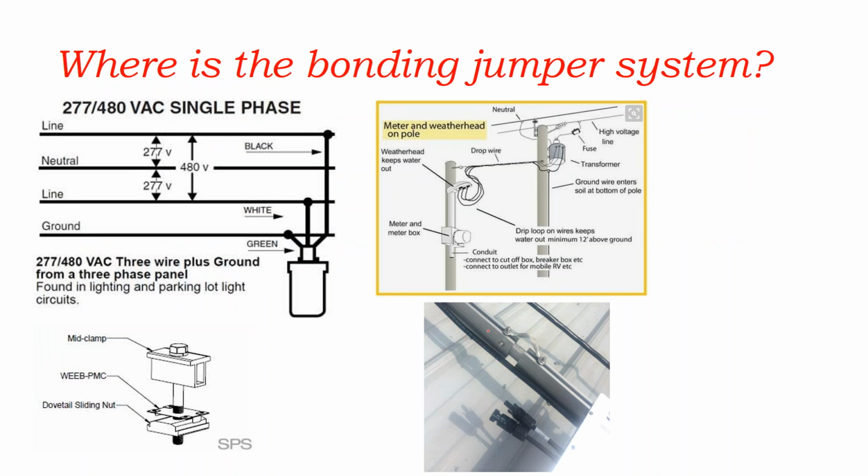One thing you need to know about bonding is all of your metal parts need to be connected. And so while that might be managed by a grounding terminal inside a box, when you get into your solar rail, normally you're going to get clips that ground the module frames directly to your module rail. So you normally have this grounded connection between your module rails. But then you get to this point where you take your metal and your other piece of metal and you install a splice bar between the two.